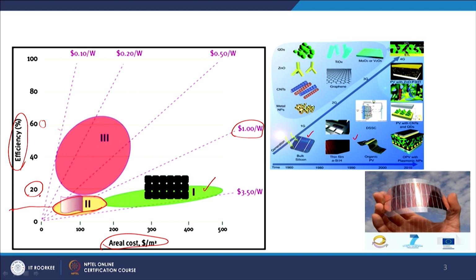At the bottom right corner, we are showing an organic solar cell, and as you can see, we have kept it between our hands. So, that means these solar cells are flexible, or this solar cell is made on a flexible substrate like flexible PET coated glass substrate. So, the advantage is that we can put it on any substrate, but a disadvantage is that if the processing of the material involves high temperature, then we cannot do it on a flexible substrate, because while you heat the flexible substrate, it can melt, because organic materials usually melt at lower temperatures.